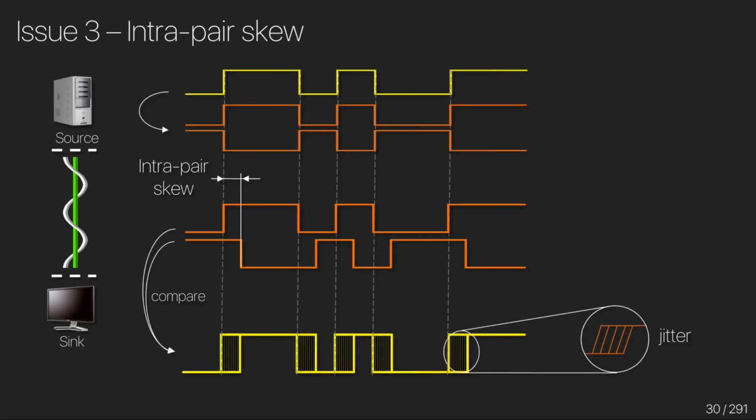And when we send the signal through the circuits to compare and reference them to each other, we encounter a problem called jitter. So the monitor needs to know when something is a high or a low, and effectively when we have jitter, there's no way of knowing whether it's a 1 or a 0. What it basically means is the transition between the 1 to the 0 cannot be predicted at what time it's going to happen.